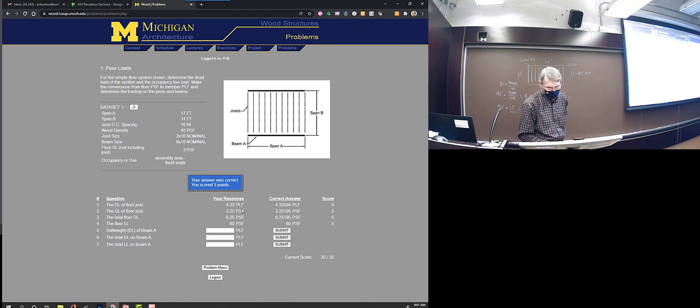And if we want the dead load, it's still got the same density, so it's the same calculation as what we did before with the joist, right? We should say 45, the density is this calculation. 45 times 85.25 over 144.